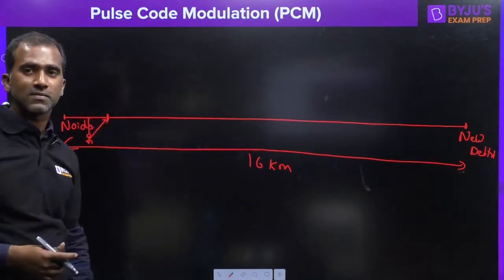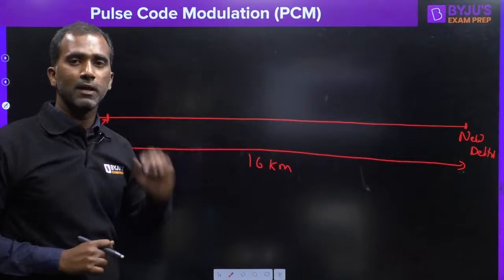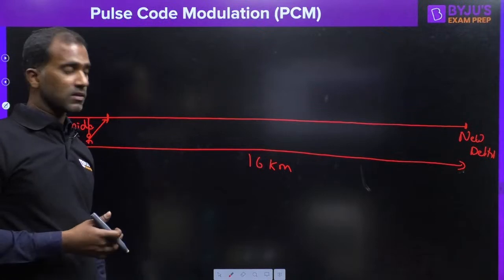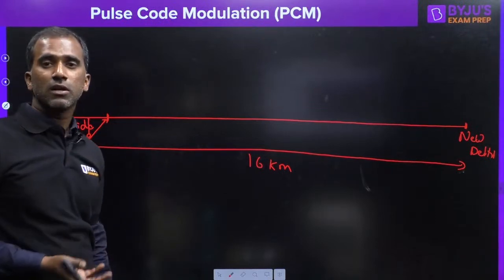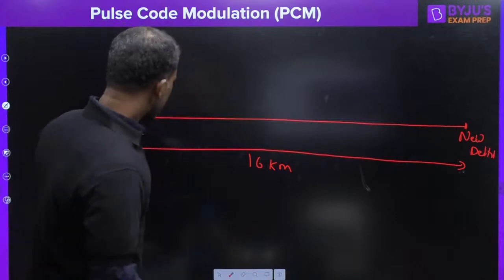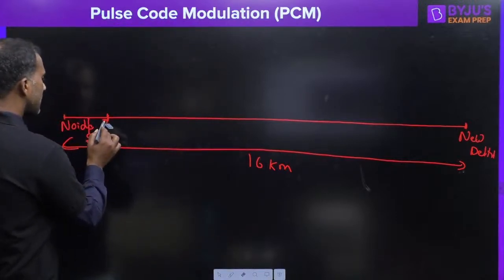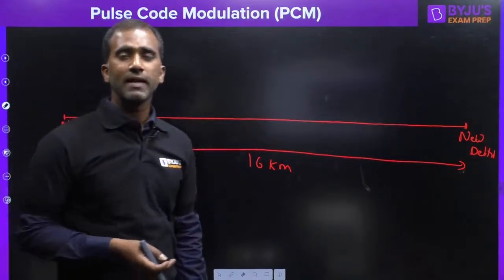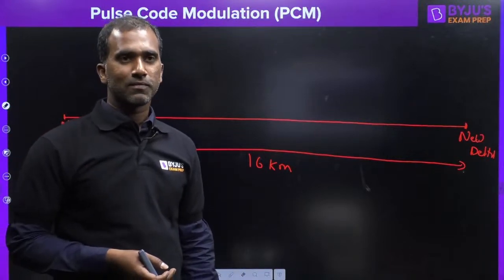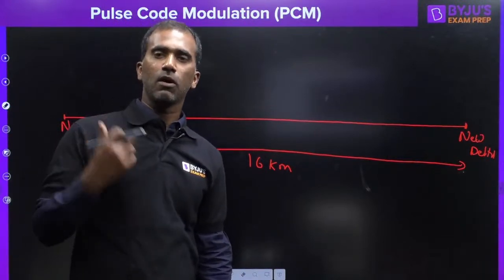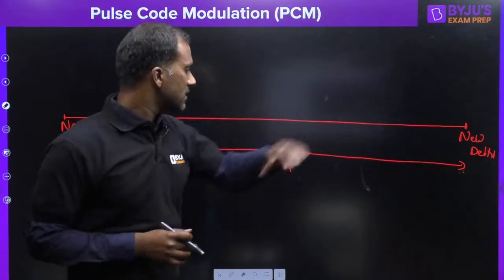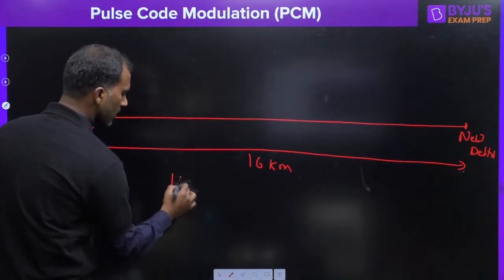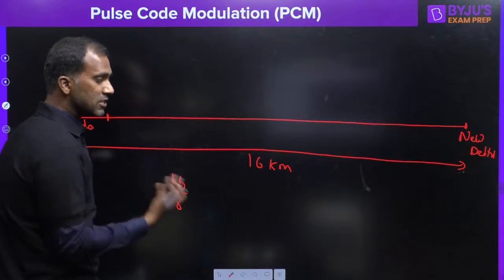Here, the walking distance, if we design the stations properly, will be as minimum as possible. If this distance to travel is more, then that is not an optimum design, right? So let's say the government has asked me to design in such a manner that there are 8 stations. If I am permitted to have 8 stations, how will I design? For minimum error for all people, I'll divide the total 16 kilometers into 8 parts, because 8 stations are allowed.